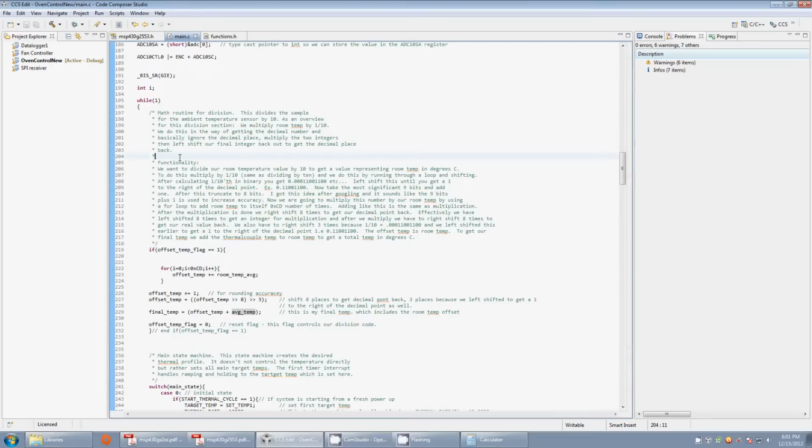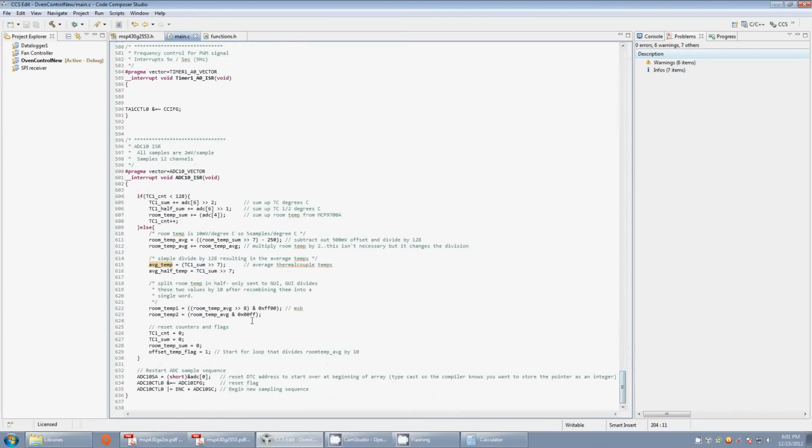I'll go over it quickly, but I'm not going to be able to explain this very well on a video. You kind of need to just calculate some stuff out and write your own routine. But remember, we just finished up the ADC video, and effectively what we need to do is take this room temperature value and divide it by 10, and that'll give us our degrees C per digit. Right now we have 10 digits or 10 samples per degree C, so we need to divide by 10. Again, from the last video, you could divide by 5, but I picked 10, and then I wrote a bunch of code to do 10, so I ended up just sticking with 10. But really you could do 5.